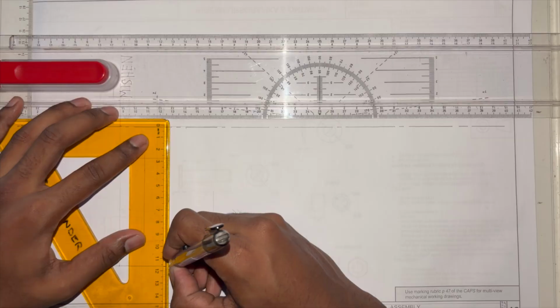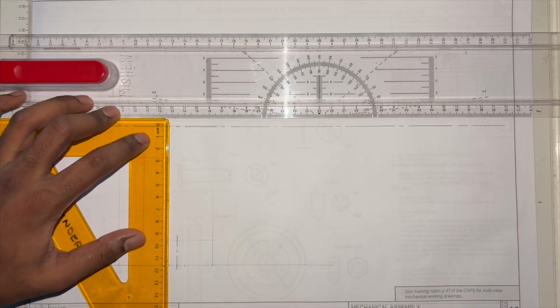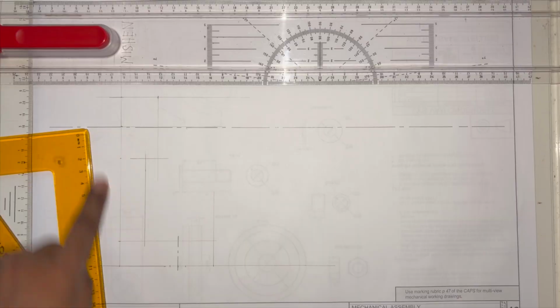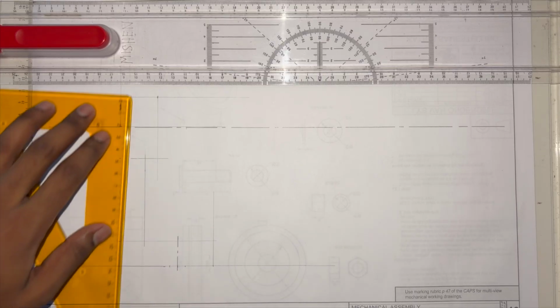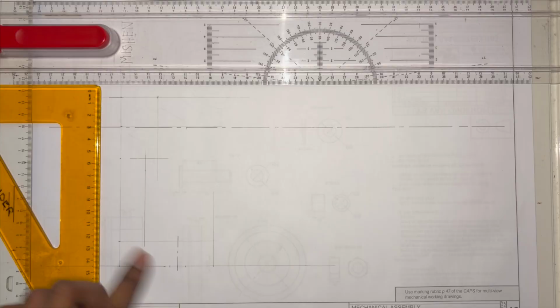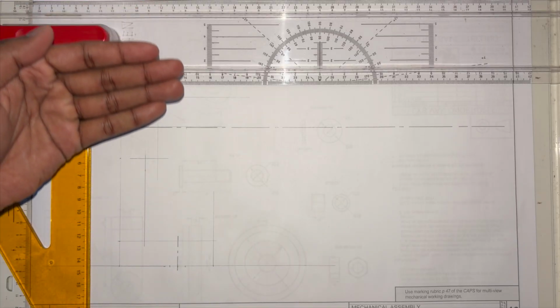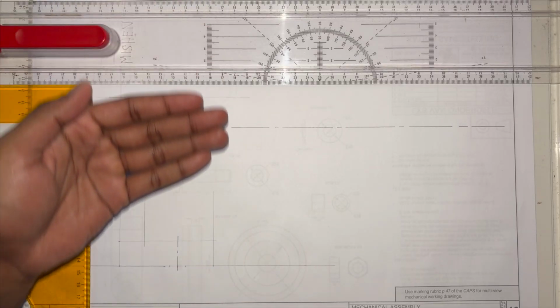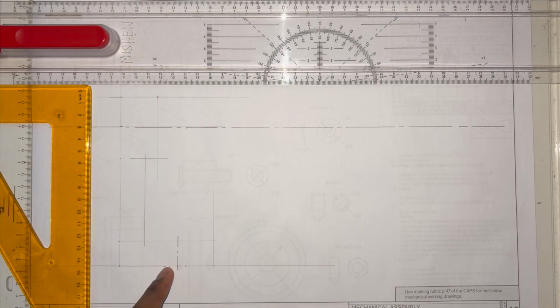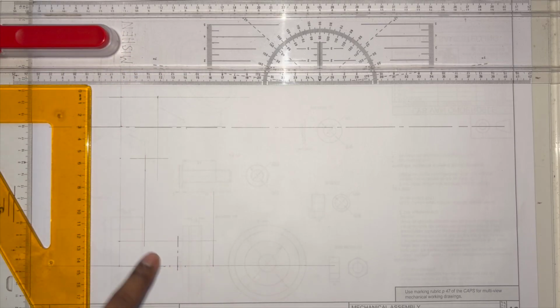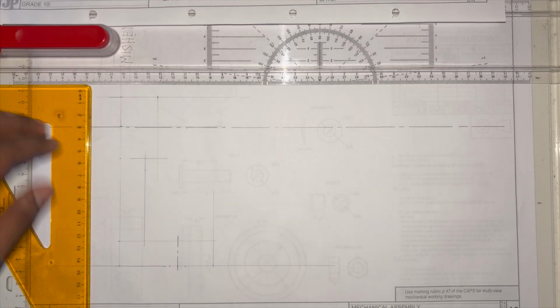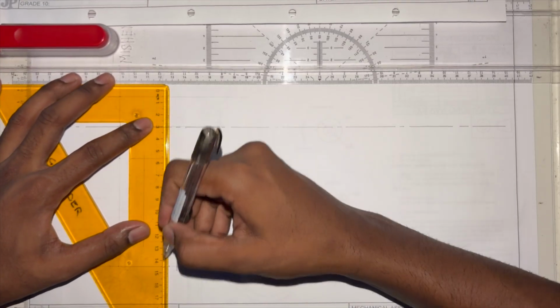Now I see a lot of students doing this consistently when they're drawing on a sectional view. This is a sectional view. They draw hidden detail lines on a sectional view, which is wrong. You don't draw hidden detail lines here. Why? Because we're cutting through the shape in half. We're cutting through the entire thing. So these are not hidden detail. They become solid lines because you can now see the material inside the shape because it's being cut. These must change to solid lines. They are no longer hidden detail.